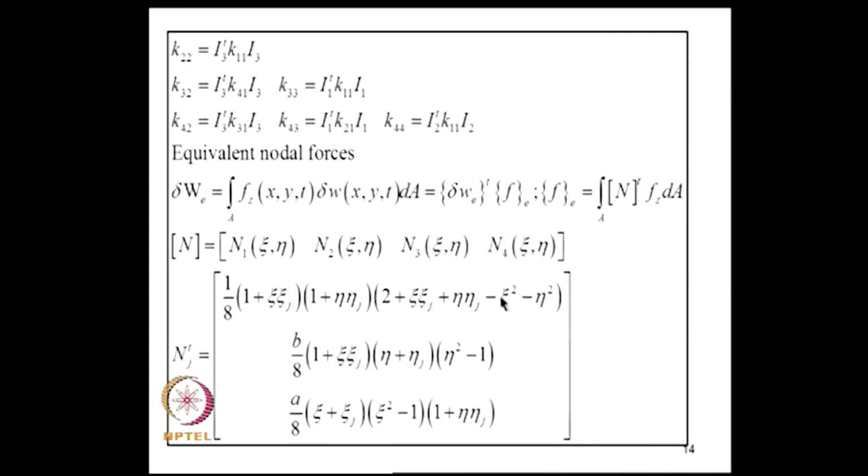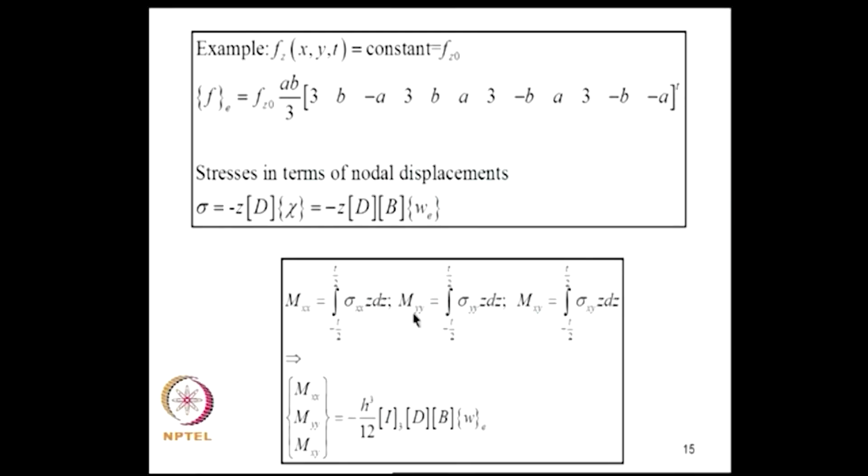Now, we need to evaluate the equivalent nodal forces. So, again we use this virtual work statement, and based on that we get the equivalent nodal forces to be given by integral n transpose f z dA, where n is the matrix we have already seen. And if, for example, this forcing is a constant load, then the equivalent nodal forces using this formulation are obtained as shown.